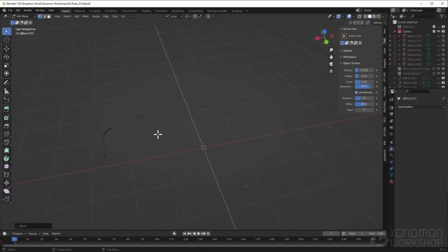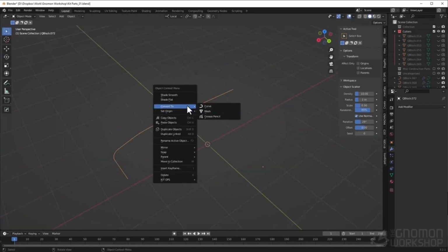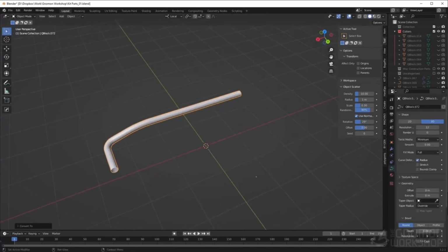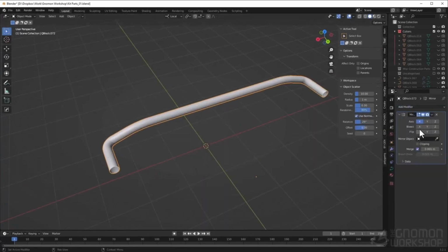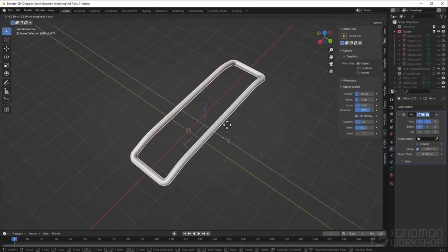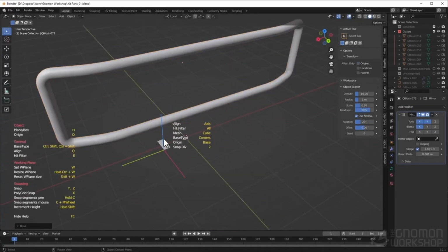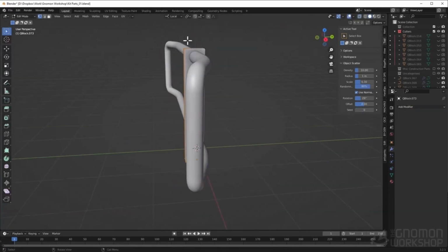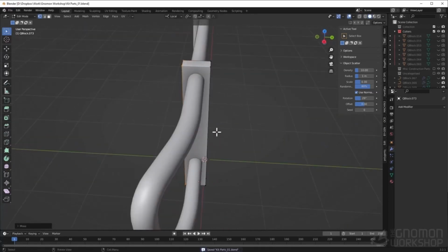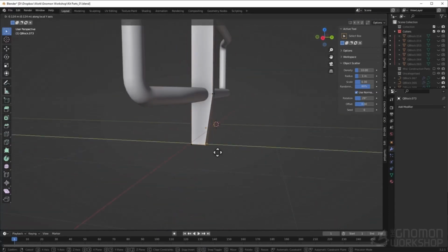I then grab the vertices and press Shift-Control-B to bevel the vertices to get a nice smooth curve on the points. I then convert to curve and add depth in the geometry drop-down. I find this a lot easier than starting off with a Bezier curve and trying to get the smooth corners with points and anchors. There may be a better way of doing this, but this is just the way I've gotten used to and it works fine.